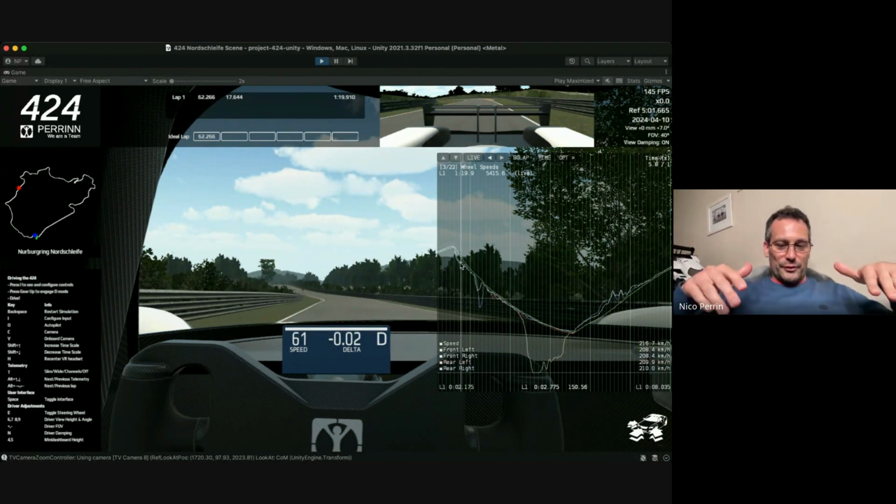The weight transfer to the front, the rear is fairly light, and any bump makes the rear sort of want to stop. So you can see one bump and a bigger one here. And towards the end of braking, it's mainly the front that you start locking. This is a big lock at the front, actually. Front left has gone to 0.